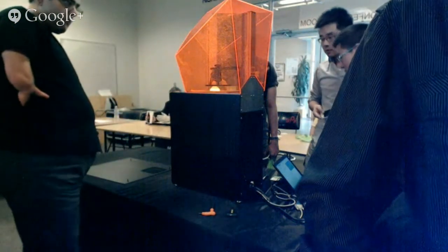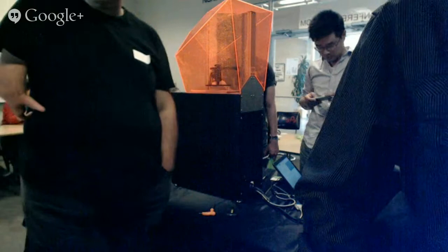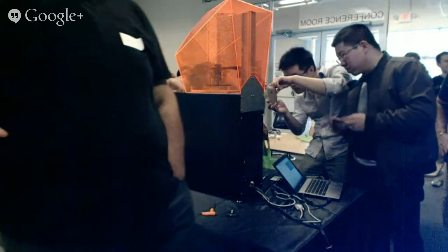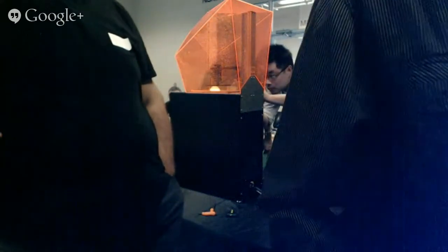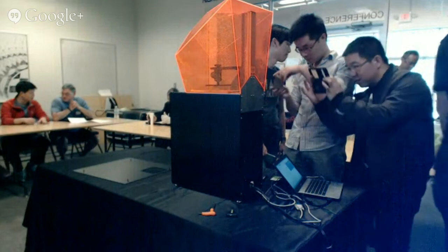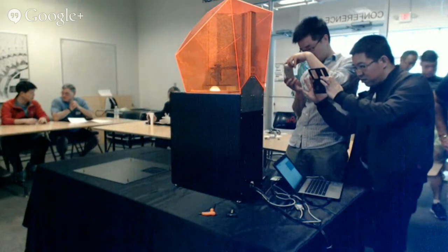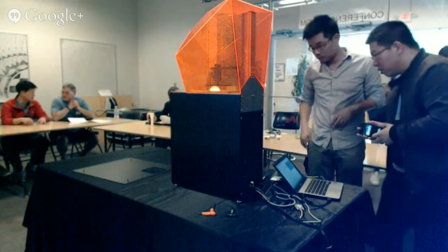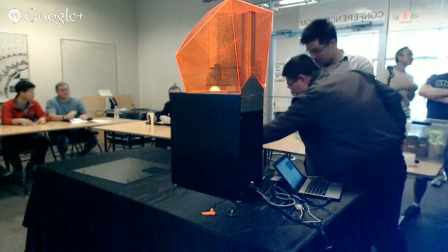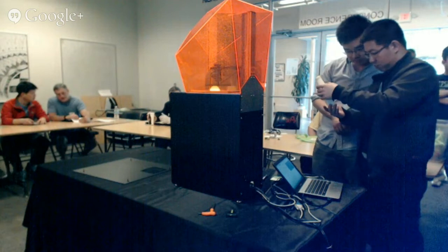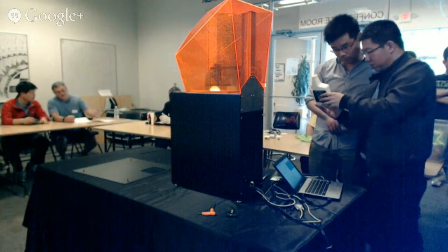Right? The bad thing is that silicone is an order of magnitude not as tough as Teflon. Right? Teflon is famous, right? It doesn't react with anything, right? It's really smooth and pretty good temperature resistant. So silicone will react with resin over time. And your silicone will start to show signs of chemical reaction after as little as 1 print. As low as 1 print. And depending on the way you orient the print, you could consume your vat, make it unusable after just 1 print.